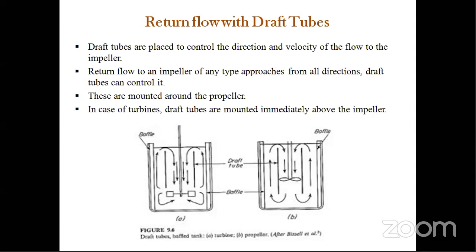The particle size decreases, or the particles break down into small particles, and are easily mixed with the liquid or easily suspended in the liquids. If you are doing the emulsion process, some amount of liquid has a tendency to overflow from the tank, but in the presence of the draft tubes, it passes again through the draft tubes and comes into the bottom layers.